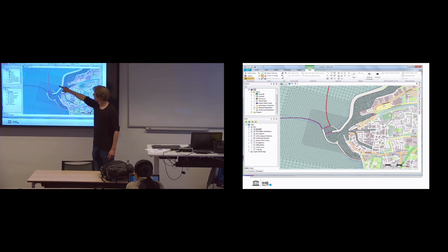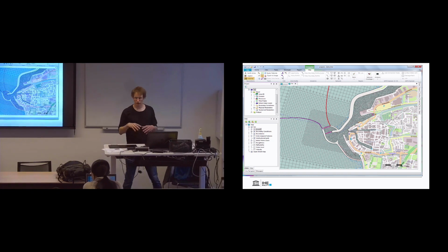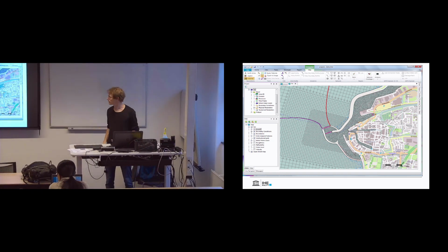And you see that you have nice resolution transitions that do not spread out in the rest of your grid. And indeed, the interface is better, so you can actually visualize your study area and make your grid a little nicer compared to just using non-boundary files in RGF grid.